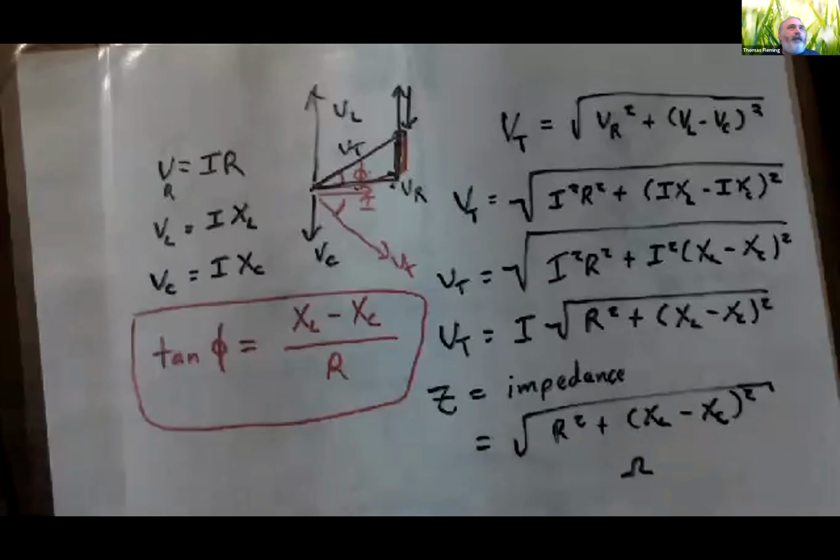Now, what I would very much like is for the current produced in my car circuitry to represent what is happening at one particular frequency for the one station that I want to listen to. And so what I do is I build a circuit that has a resonant frequency that coincides with my particular radio station. And so what's going to happen is that one frequency will cause lots of current to flow through my speakers, and I'll hear that sound.